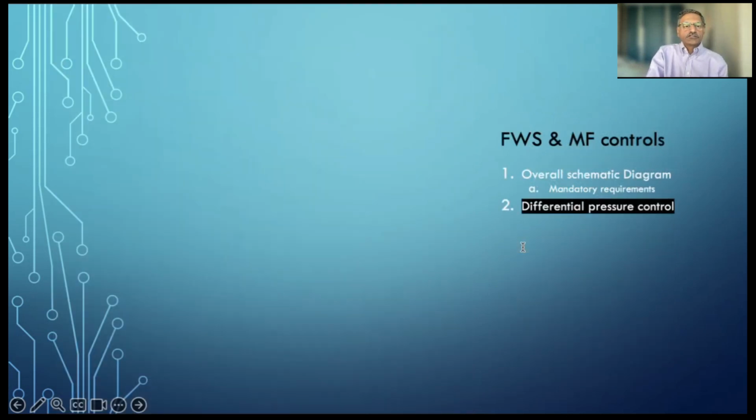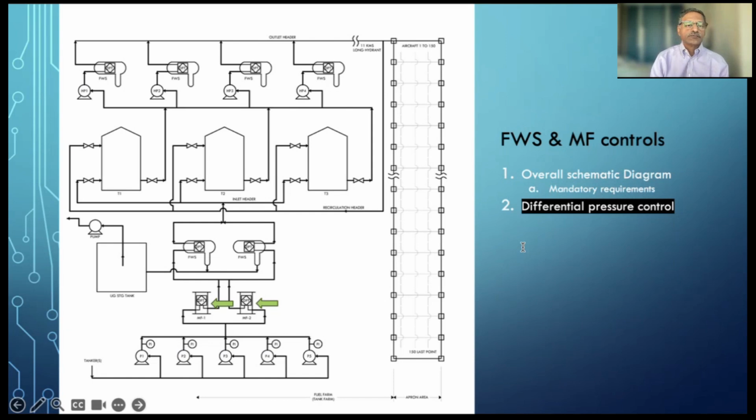So the first thing, when I said the first thing is microfilters, right? Microfilters are required because, imagine, the fuel is coming from the refinery through some pipeline, through some tankers, then it is coming to this fuel farm. So all the way there can be rusting, there could be microparticles in the fuel, and those are to be eliminated. So first, when you are putting the tanker product into the tank, you have microfilters. The green arrow shows there are two microfilters which will take out all the sedimentation and dirt which has come.